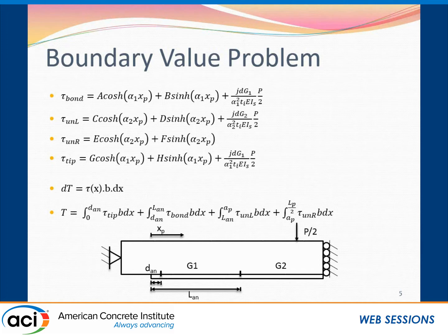In order to obtain the total force in the interface, we integrate the shear stress over the span of the FRP plate. It's worth noting that in order to simplify our model, we just included the first and the last active anchor. So we might have more anchors here in this bonded region. However, the model accounts for only two anchors at a time. And then we expect that in between the same behavior occurs since it's still fully bonded.